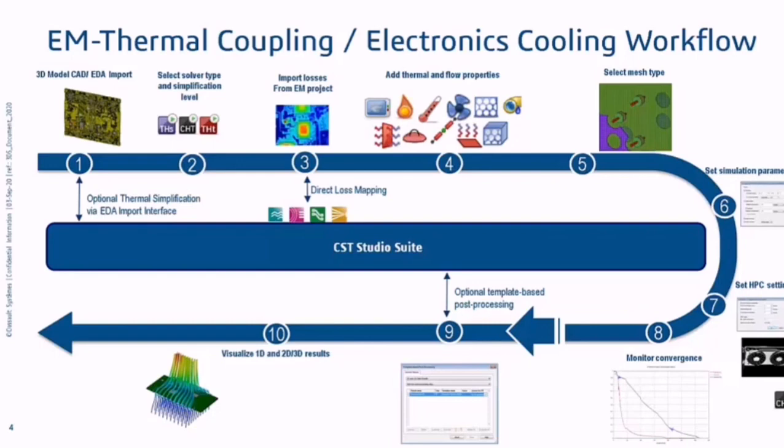Do the mesh, simulation parameters, possibly acceleration settings. The CHT solver can use GPU acceleration, do some post-processing, and of course visualize the results to take a look at what kind of temperatures we actually do have there.